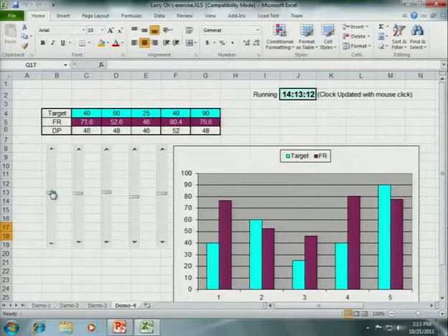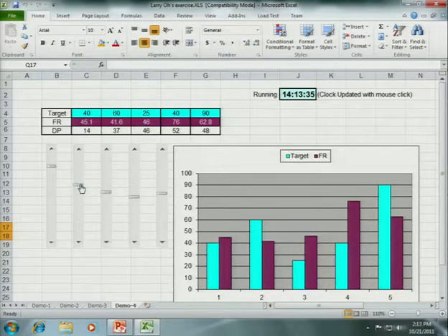And so as I adjust DP1 to try to get FR4 in tolerance, I'm looking at what's happening to the value there. I'm just about there. Whoops. Okay, so I could call that close enough. And now I start adjusting the next one, and we see that FR1 is now out of tolerance because there is some coupling. So you can try to figure out what's the right order of adjustment in order to adjust the DPs to satisfy all the FRs.